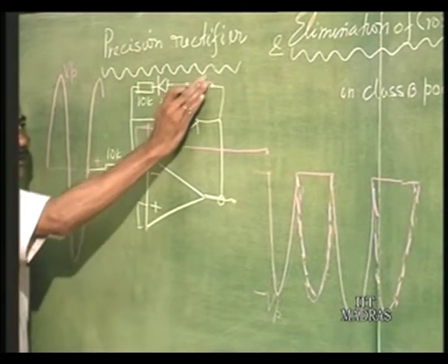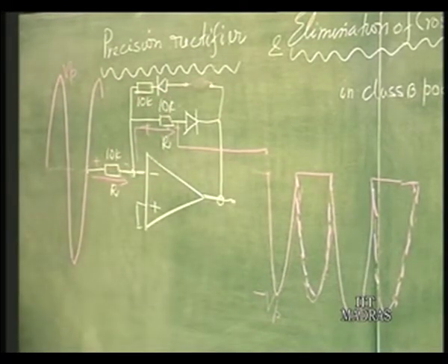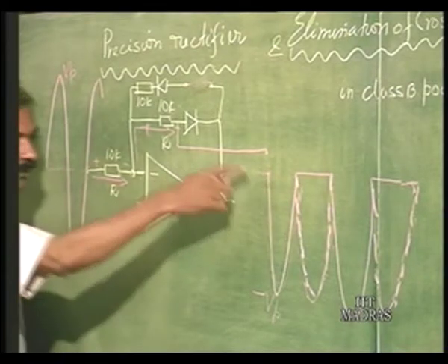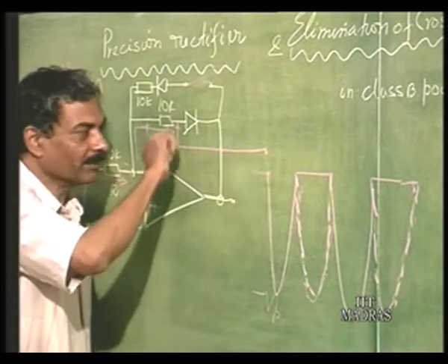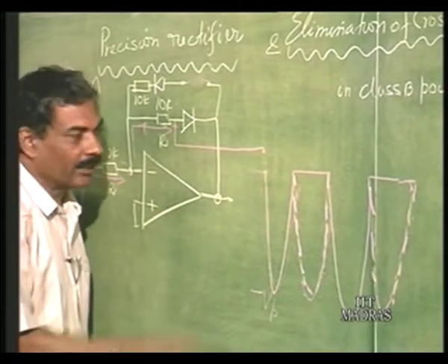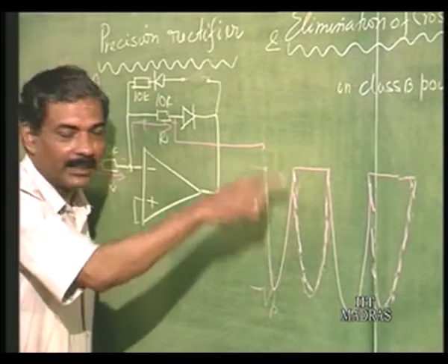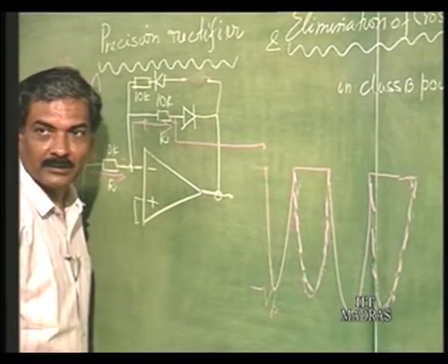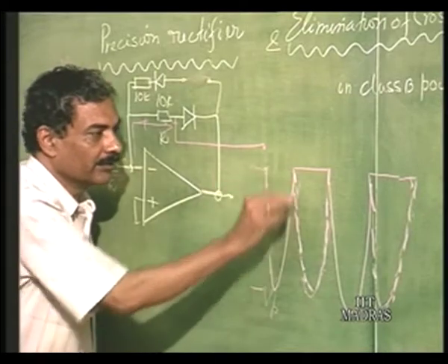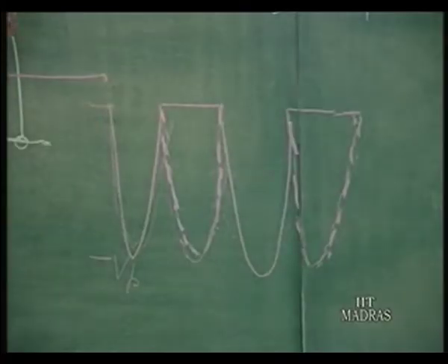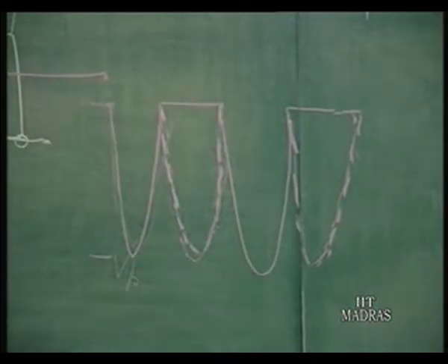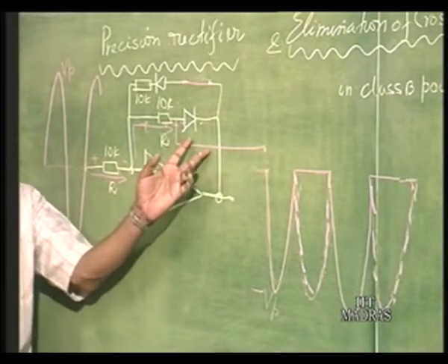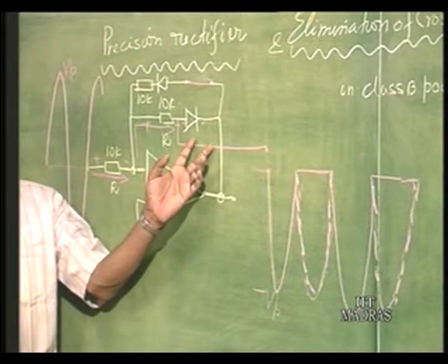So, we will see the demonstration even if this is not connected purposely to see whether we get this waveform, and you will see that this amplitude is different from this, okay. It depends upon the amount of loading it has. I am connecting an oscilloscope here and all that, even that may load to a certain extent this, okay. This waveform is seen, then the moment this is shorted, you will see that this is clamped to 0, okay. This demonstration occurs, and this is independent of the cut in voltage of the diode, okay.